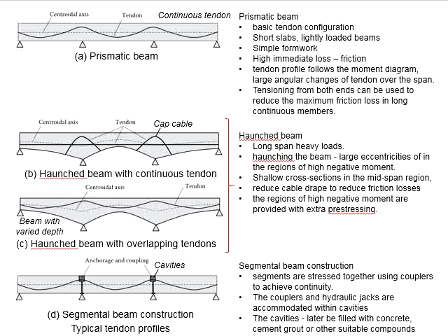If you wish to minimize the frictional loss, ideally you will have the tendon profile in a straight line. Although the tendon profile is a straight line, because of the changing position of the centroid axis, there will be effective eccentricity between the central axis and the position of the tendon.